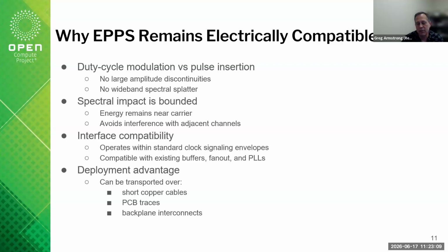And handle that very low frequency pulse and make sure you generate that very clean, high-quality edge as a fan out or something like that, right? You almost have to have a very specific buffer just to support the 1 PPS. And especially if you're going to drive it over a cable, then you need a very specific driver to make sure that signal is not perturbed going over that coax cable, because you don't know the distance it's going to be running. So for interface compatibility, we can now use standard CMOS signaling. You can even use differential like HCSL to distribute that clock. Really, it doesn't matter what you use because it's all compatible using EPPS versus a 10 megahertz signal.